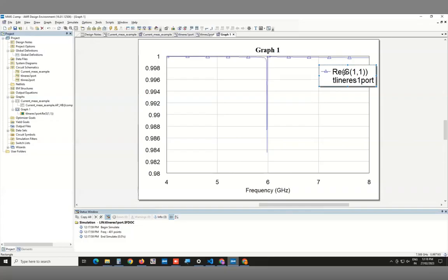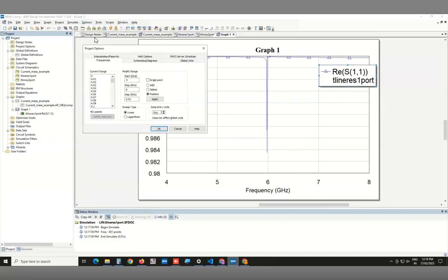So what should be the natural instinct there? It's like, okay, it looks like all the action is right in the middle. I don't need to sweep such a big frequency. So you go and you change the frequency range so that you can see what is happening. I think in some cases, you saw that there was nothing and that was it. That was the end of the problem. So let's go to somewhere closer. I mean, this looks fairly close to 6 gigahertz.